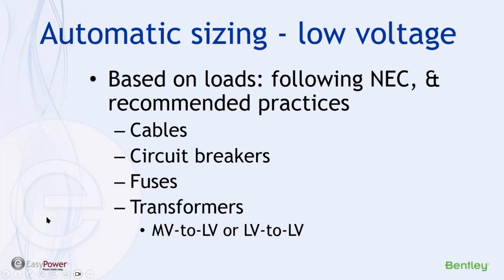What it does do is provide automatic sizing for low voltage equipment, based on the loads, and it follows the recommended practices of NEC and IEEE recommendations. It can size cables, circuit breakers, fuses, and transformers, specifically medium voltage to low voltage or low voltage to low voltage transformers. So it's not a catch-all. We'll get into more of that as we go through this.